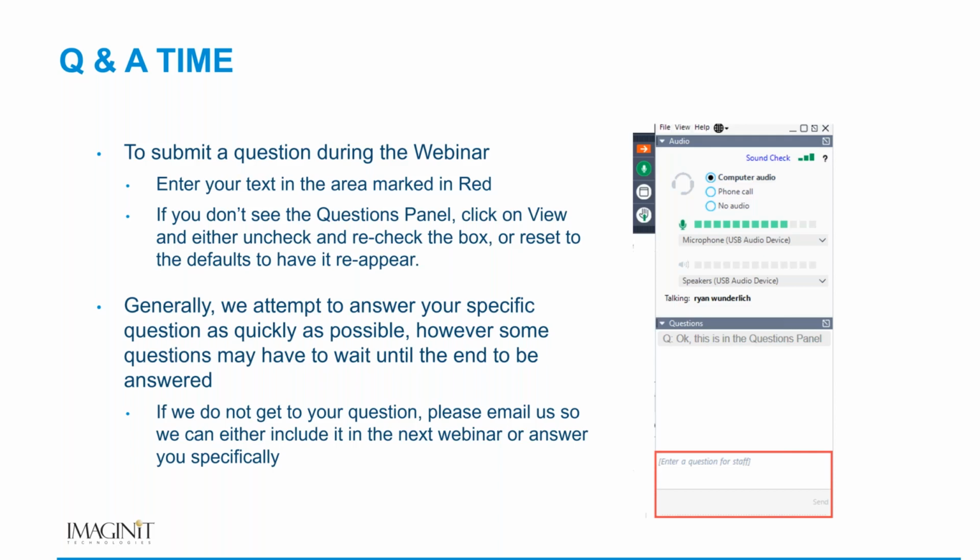That AutoCAD Electrical makes good P&IDs not linked to Plant though. Yes, you can use AutoCAD Electrical to make P&IDs. You're gonna have to build some custom content in order to make that happen, because P&IDs are not the same as schematics, which is what AutoCAD Electrical is really good at, making schematics and circuit diagrams.